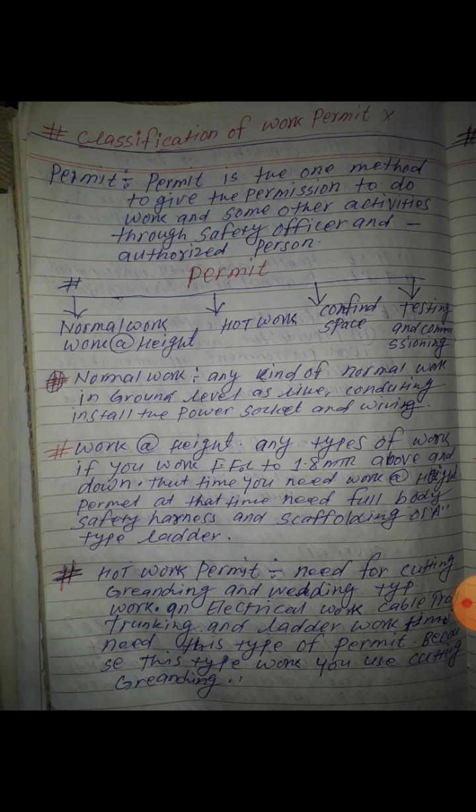Okay, so what are the hazards in confined space? Confined space has some hazards, so you control the hazards, and then after that you start the work. And the hazard is controlled with your safety officer. Okay, so what are the hazards? There are harmful dust and gases inside. Okay, so these gases must be controlled. Insufficient oxygen, because fresh air is not passing in, and there is insufficient oxygen also. So care about this one.